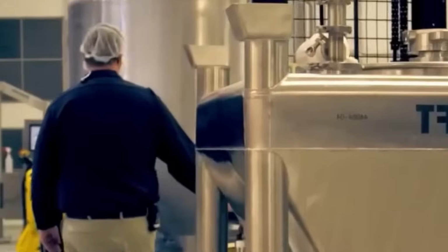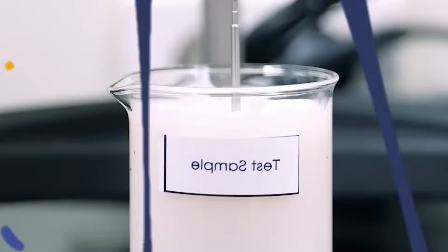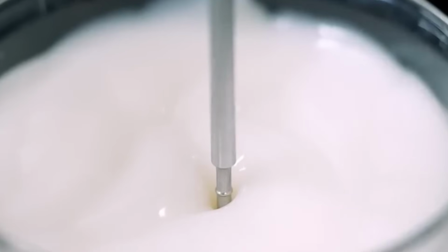Hydrocolloid binders such as carboxymethyl cellulose, xanthan gum, or carrageenan are pre-dispersed in warm water before being added to the mixture. These agents control rheology and prevent phase separation. Dispersion tanks use overhead agitators operating at low RPM to avoid clumping. Hydration time is monitored to ensure full polymer expansion before integration.